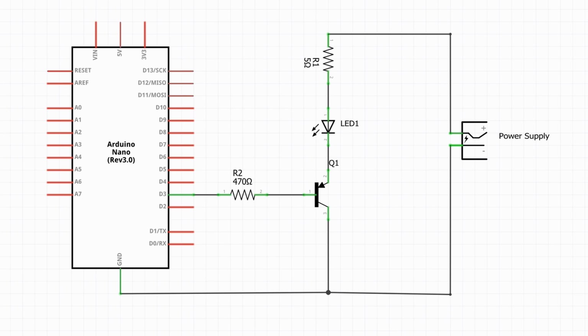Why would we need PNP transistors? We can exchange the NPN with a PNP type. As we learned before, the diode has to conduct if we want the transistor on. In this case, we have to switch the transistor on by putting the pin to low or 0 volts. If the transistor is on, it should behave like a short circuit, and the voltage here has to be close to 0. Unfortunately, then, this diode does not have the needed 0.6 volts to switch on.